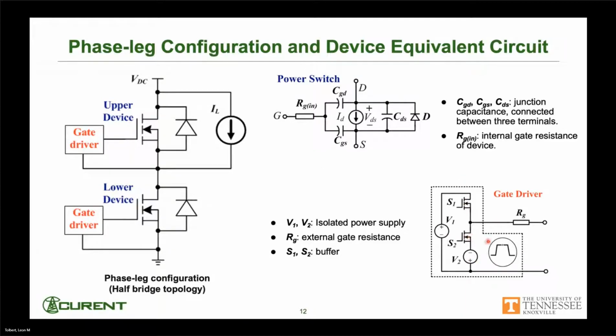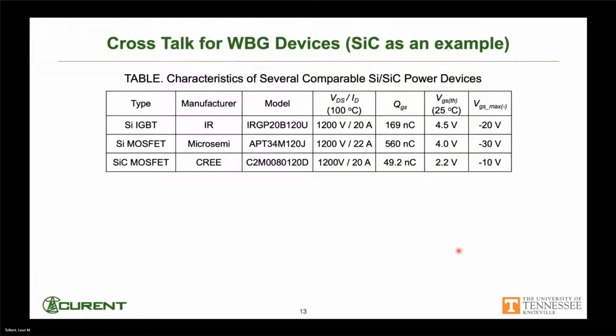A typical gate driver is shown here on the right. Basically, you typically have a couple of voltage sources. This top one, V1, is when we turn it on, and that's this higher voltage here, which typically is something like 20 volts. And then this voltage source is when you turn it off. It's negative, maybe something like -2, could be as much as -5, and some people just use 0. Typically, there's a negative voltage there to help you turn it off more quickly, and to keep it off so that it's not susceptible to spurious noise.